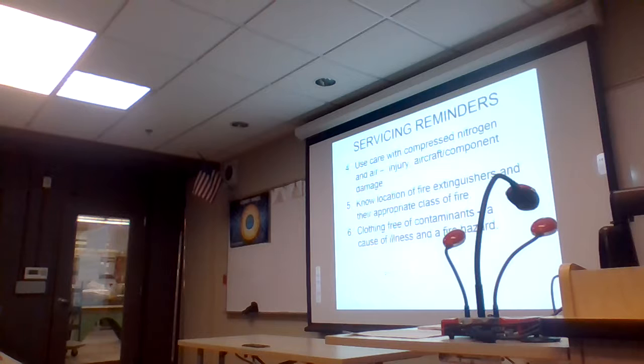Clothing free of contaminants, causes of illness and fire hazard. Oh boy, I can tell you a little bit about that. Some of the hydraulic fluids are flammable by nature, like MIL-H-5606. The last thing you want to do is walk around with clothing saturated in this stuff, because you're a walking match. So it's not a good practice. In addition, there are some additives in hydraulic fluid that are hazardous to your health. They're great things for hydraulic fluid, but they're not great things for your body.